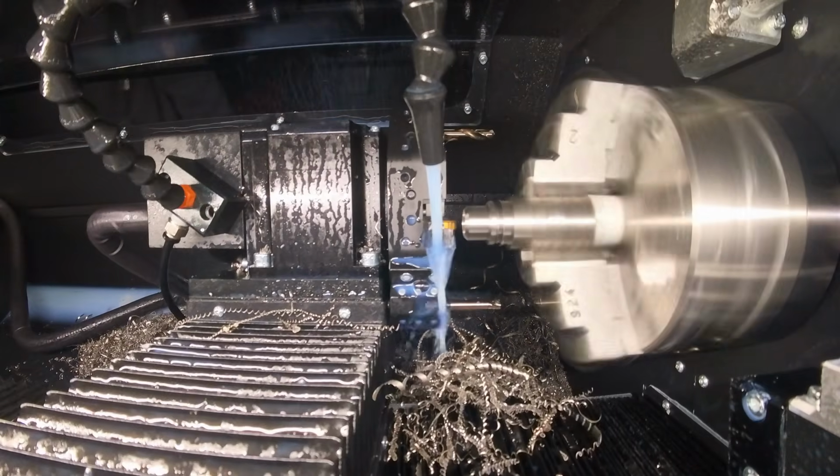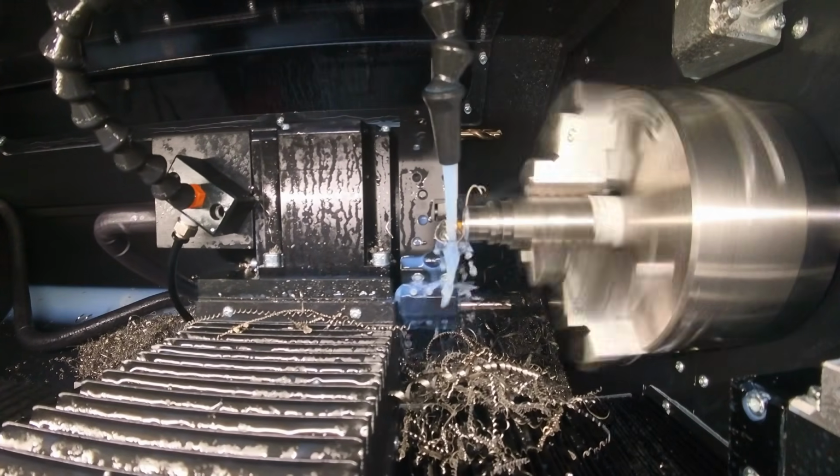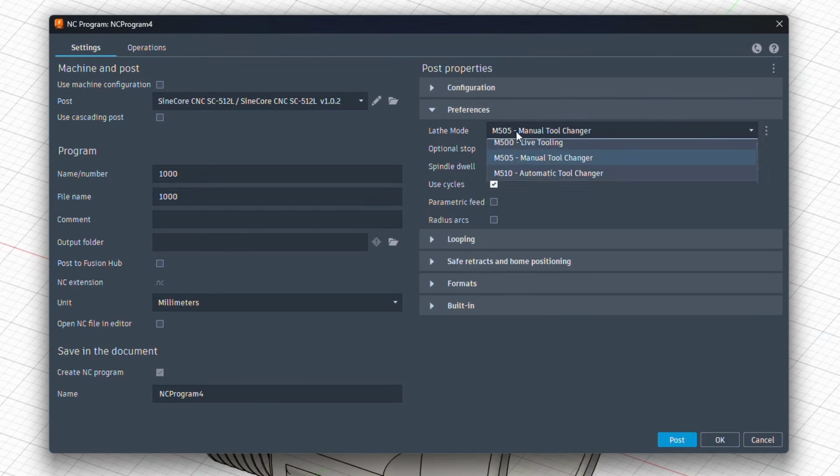Because each mode changes how the machine behaves, it is important to confirm the correct mode before starting a job. When creating programs in Fusion 360, make sure you select the correct mode before posting and running your program. The mode selected on the machine should match the kind of setup and operation your program was made for.